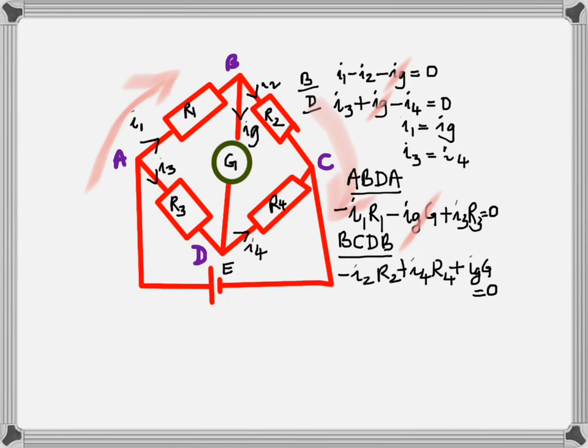Now, again, remember Ig is 0, so what happens to the product? Wherever you have Ig, you put a 0. So Ig becomes 0 there and also in this, so this term also crosses out. What do you have now? Don't you have I1R1 is equal to I3R3?